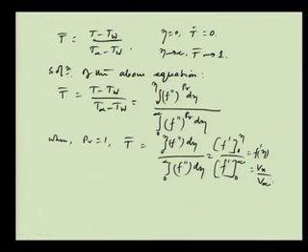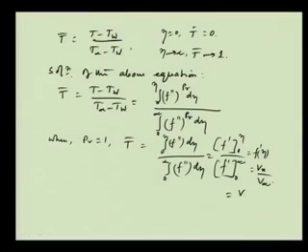So, we can say that dimensionless temperature and dimensionless velocity are the same, they are coinciding with each other. That is what we have already seen, that for Prandtl number 1, both the thermal boundary layer and the hydrodynamic boundary layer coincide over each other, and that we can also see from here. So, this is equal to Vx bar, the dimensionless velocity. Okay. Now, they are coinciding with each other.